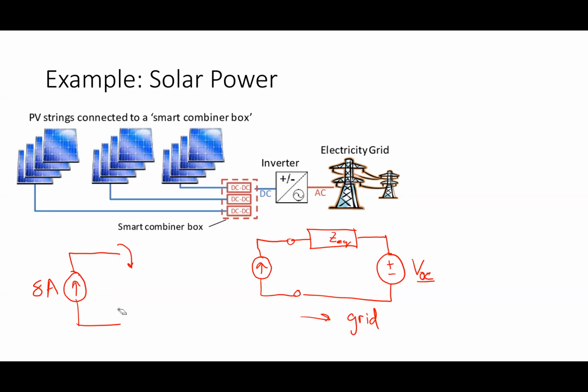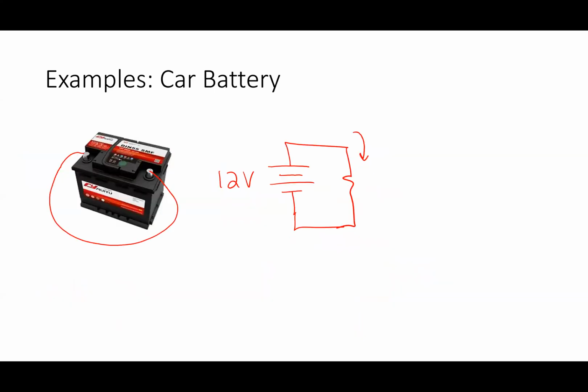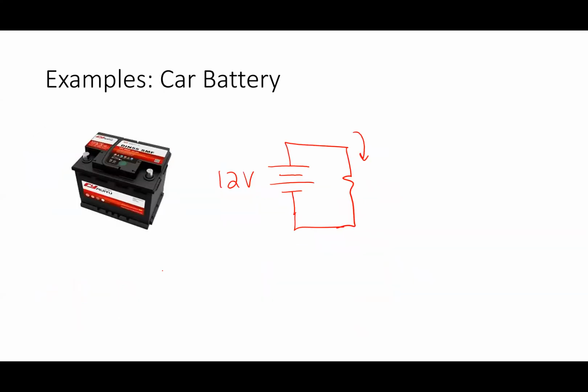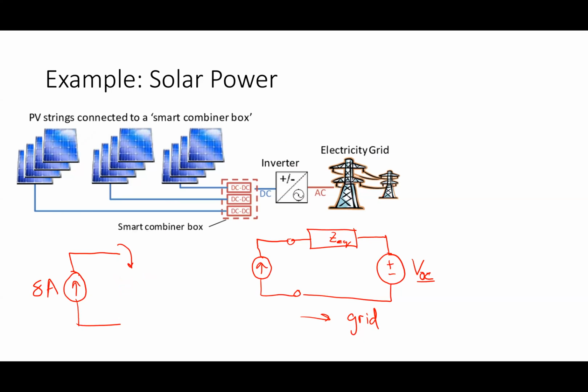Opening a voltage source is fine, because it just has no current. Shorting a current source is fine. Now I say that because in the case of a battery, the circuit, in this case this R, determined the current. In the case of a current source, the R I connect determines the voltage. That's an important point, and I make it because we're going to use it right off the bat when we get into mesh and nodal analysis.